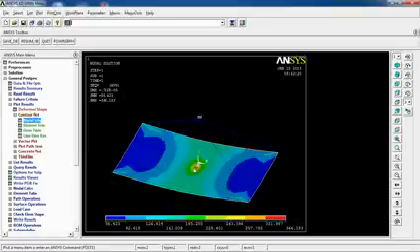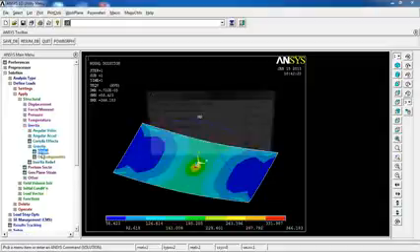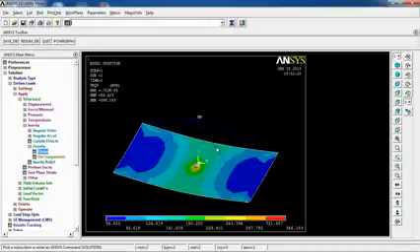One thing I wanted to add to this model was gravity, but again, I tested this before, and because of the limitation of my version of ANSYS, the displacement of the model was going above a limited value. But you can also practice that. You can come to solution, define and apply gravity to your model, and see how your model would behave if there was also weight and gravity applied to your model. With this, lesson 9 is concluded.